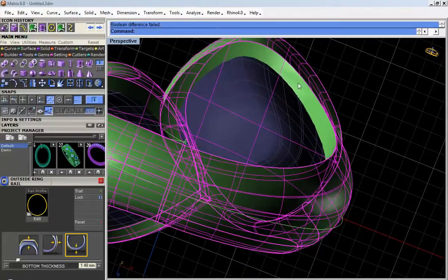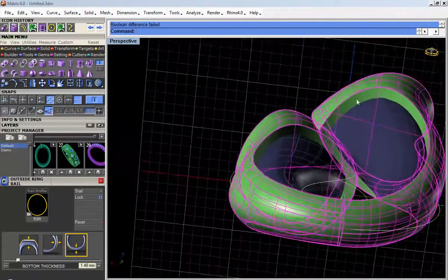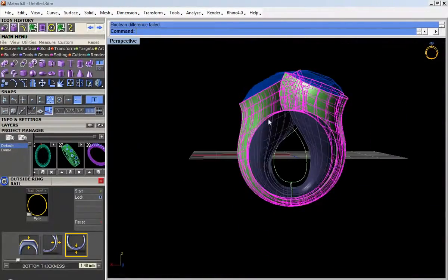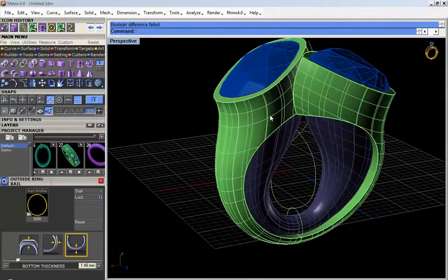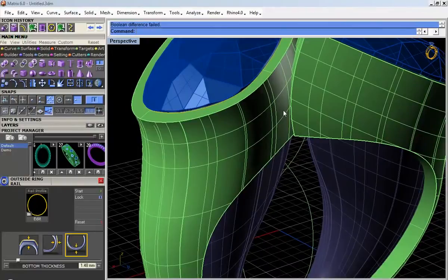We need this one because this is the 1 mm offset we did. I'm saying now we cannot cut them. But the reason is something else. That's because this object is one. If it's one, it cannot intersect itself. It has to be union.